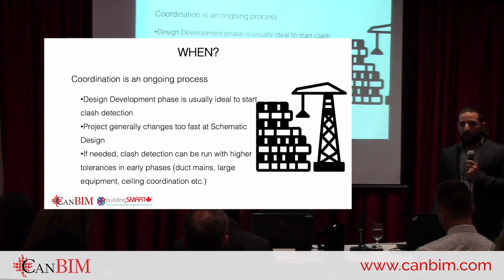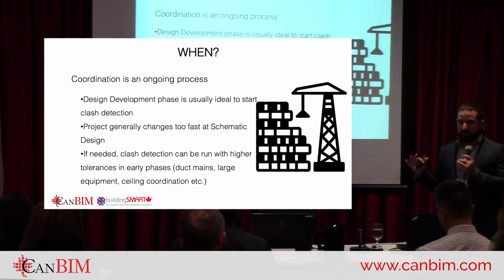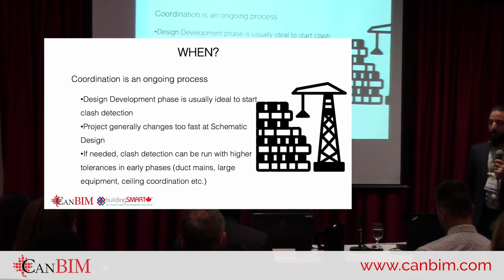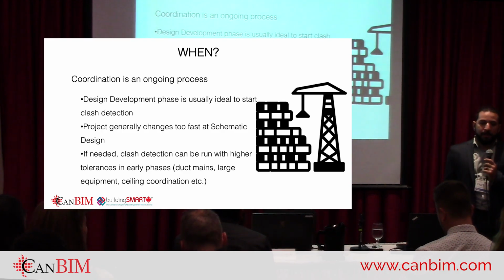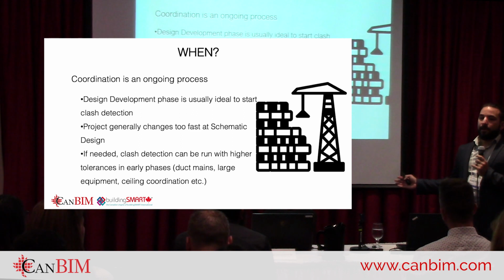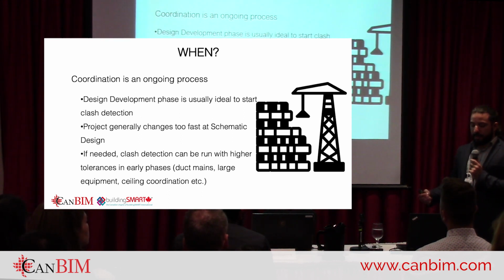And I think in my experience, this depends on the project type, because I've seen projects where you have one project that has like 7 different submissions, and they're all in different phases. So it can get complicated. But in general, I think design development is a good phase to start this process, because in schematic design, you're still moving items around way too fast. A clash you find today is probably not even going to be there tomorrow. They may completely change the design.